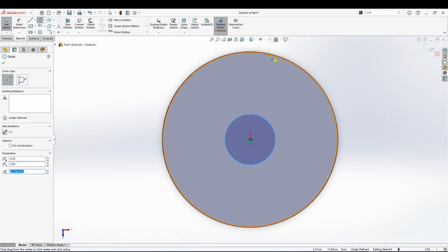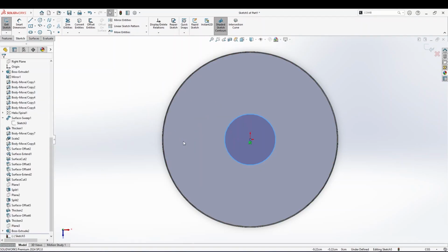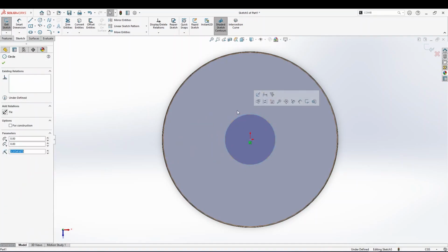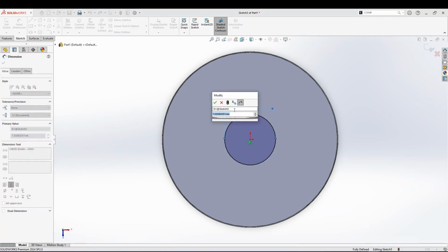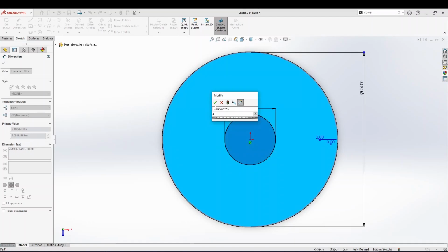The radius here was 12. Okay, let's make the circle 3 times smaller. Let's press escape from this circle drawing tool. Now we take mouse gestures, right click, drag upward. Once it's chosen, once again drag upward, we press here, and we make this radius 4, 3 times smaller than 12.